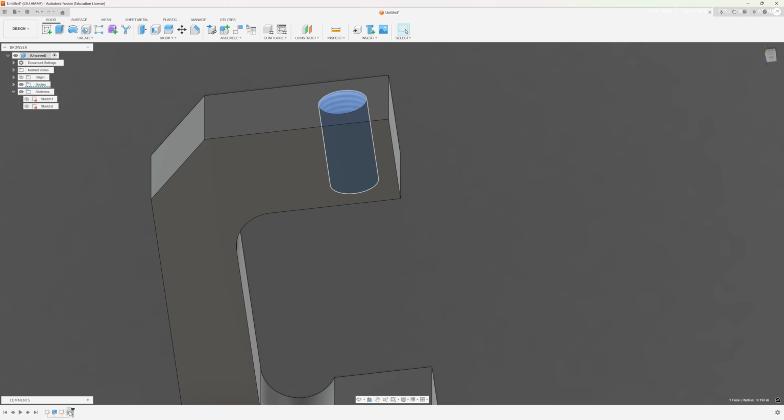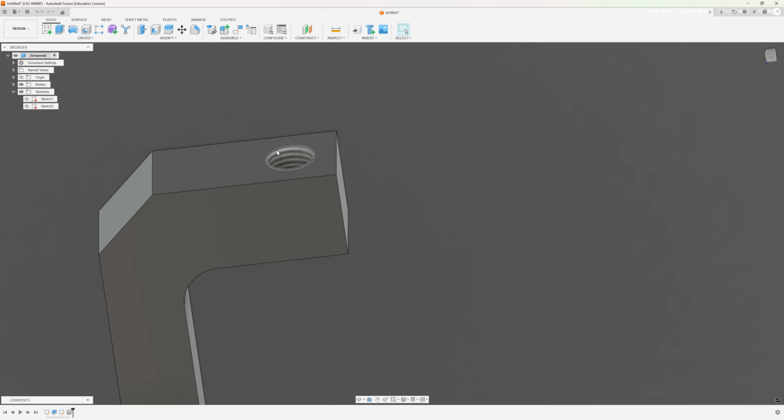It allows me to remove some of the guesswork from the machining process, because I can see that it has cosmetic threads, I know that it needs to be tapped, but what do I need to tap it with? I can do some guesswork based on the tap drill size and get close, but I don't know for sure. By naming it what my tap drill size is, I'm going to save some of that guesswork for myself or other machinists down the road.